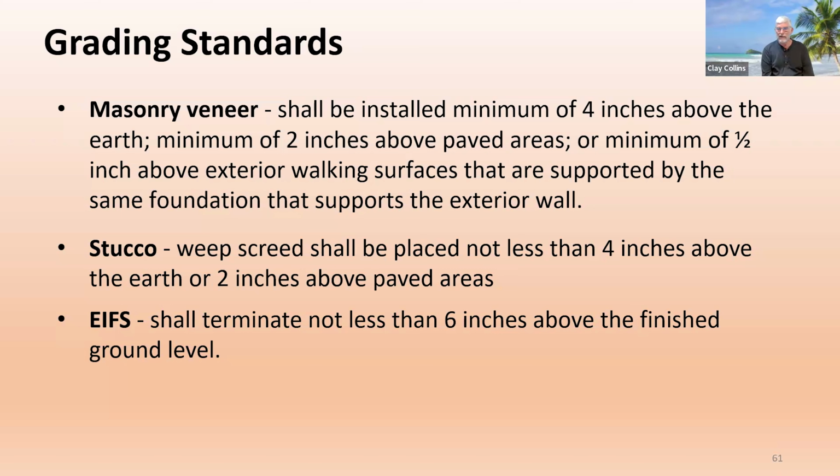Vinyl siding gets used to cover up, at least down here, again, geographic competency. I don't know what y'all would experience north of us, but we have a lot of vinyl siding that gets applied on top of homes that were built in the 70s with that cardboard siding. If it's covered with vinyl and you still have a small amount of clearance, I call it out because we don't know what's behind it. We can just almost guarantee that they overlaid it rather than replaced it. The whole purpose of them putting the vinyl on was to save money.